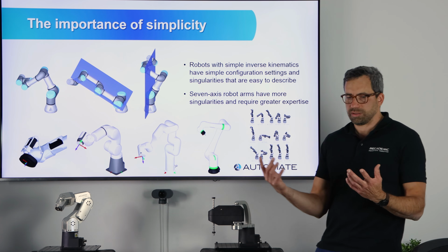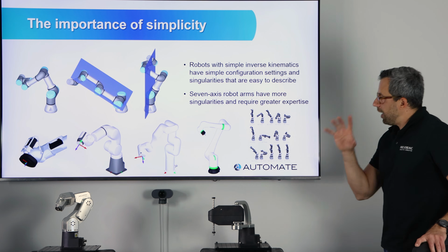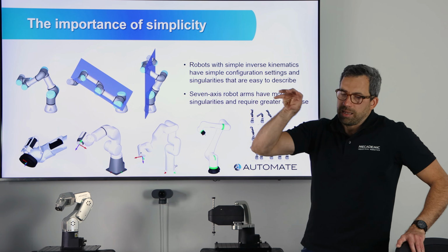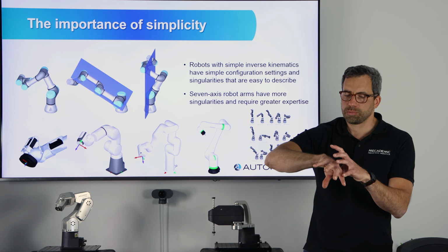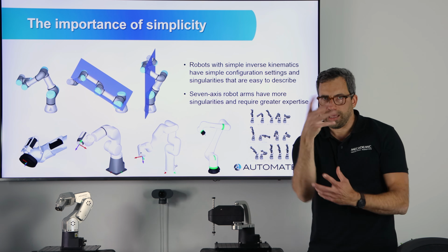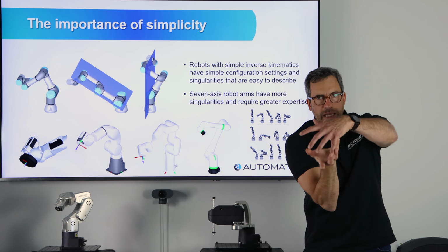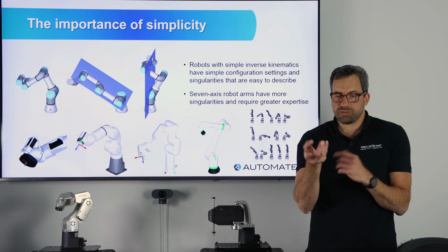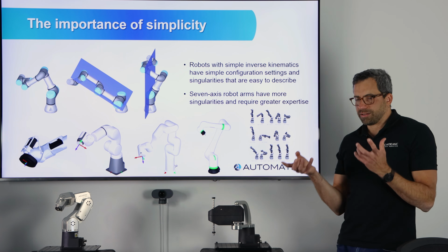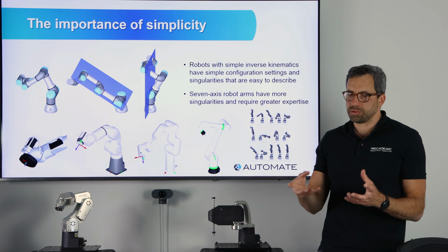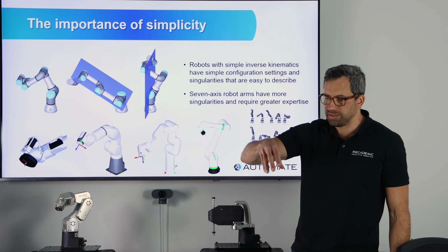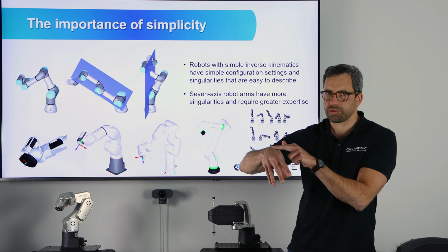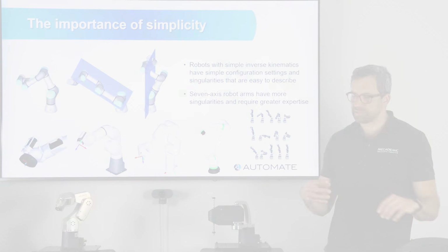You don't know. It's very, very complex. And again, with some of these robots, you can start from one robot position and then move to the same robot pose without crossing a singularity, which is dangerous, because basically there is no way of specifying to the robot, I want you to visit this end effector pose always with the same robot configuration. So this is kind of dangerous.